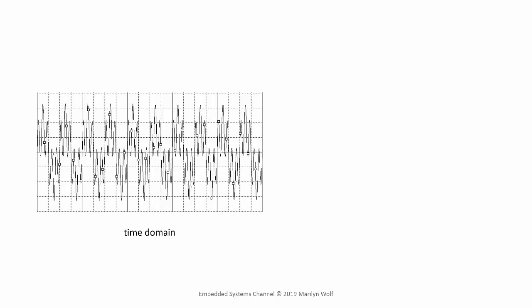This shows a time domain version of a signal. This signal looks complex, but when we look at it in the frequency domain, we can see that it's in fact composed from two different sinusoids, omega 1 and omega 2. The axis represents frequency, and this frequency domain plot shows that our signal has two components.